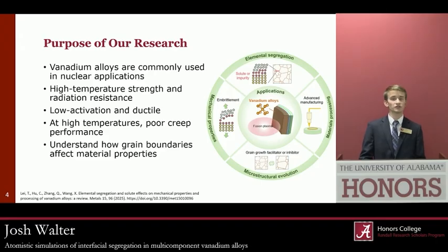So for our research in particular, we are studying vanadium alloys. Vanadium alloys tend to have a lot of uses, but one of their primary uses is in nuclear applications. The reason for this is their high temperature strength and radiation resistance. Vanadium alloys tend to be very low activation, so they don't have negative interactions with radiation, making them great candidates for these uses.